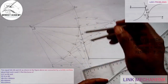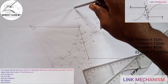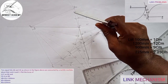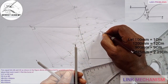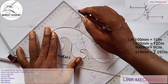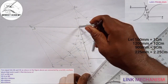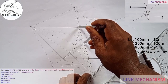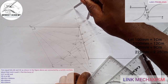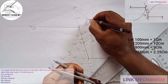Similarly, I'll come to B and D again, come to B12 in order to get the point. So you're looking at this point here and here. So that will give me my D12 here. I'm going to join D12, B12 this way. So I need a midpoint between B and D with BP. Come to D12, meeting at this point, right? In order to get P12. P12 here.